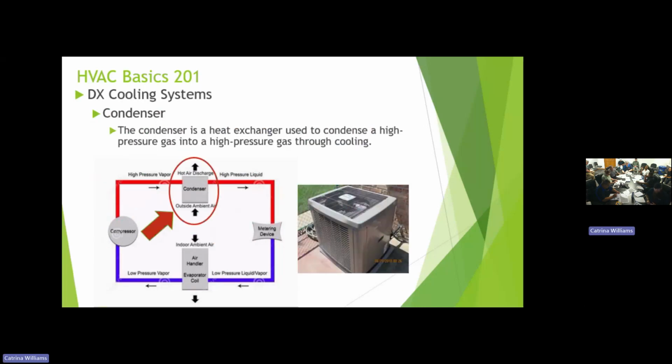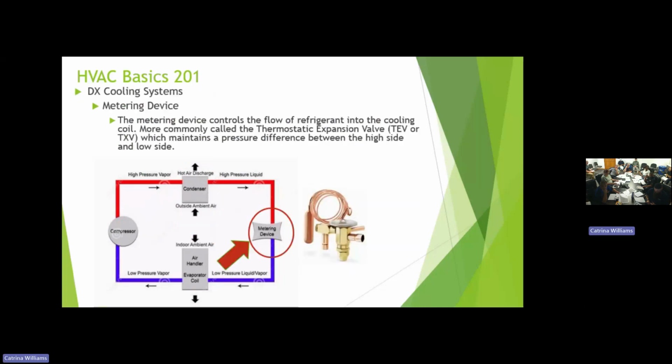Then once it leaves there, here's what outside is going to look like. Compressor down here below, the bottom part, you have a condensing fan here. It's going to exhaust the heat. Here's the metering device we mentioned. This is the metering bulb on the coil that controls the flow going through it. It goes from the high pressure liquid, and that controls how much comes out to a low pressure liquid/vapor to get the cooling effect that we need.